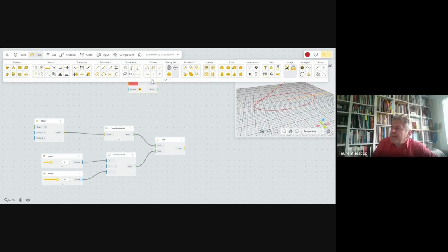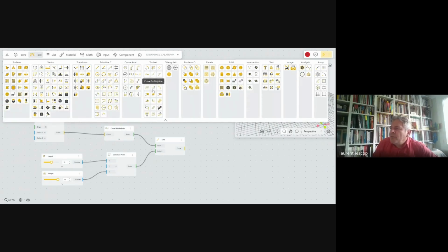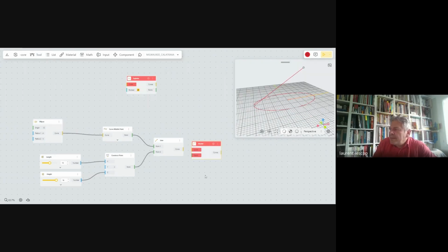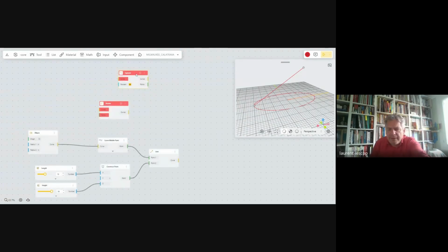With shattering, you can say precisely where you want to cut the curves. There are many ways to do it. I could have used a line to say, okay, I divide from this line. What is interesting with shattering is that you just have to indicate one point or two points, and then it will work. So this I will suppress.